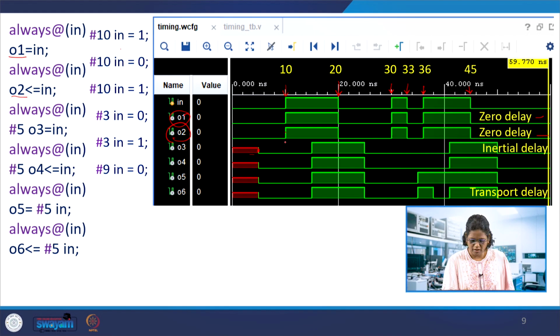After this 5, the 10 change is reflected at 15, you can see over here, this is 15, because of the delayed evaluation, and then this change would be reflected here. So what happened to the 30 change, which is not reflected? It is evaluated before assigning, that means it is after 5 time units.